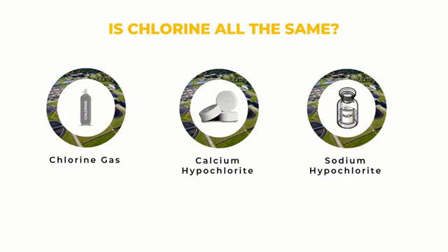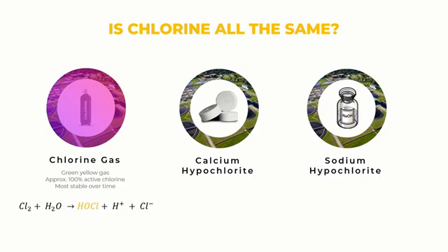Chlorine gas is greenish-yellow in color and heavier than air. Its high toxicity makes it an excellent disinfectant for water but also a hazard to humans who handle it. Because of chemical changes that occur when it is introduced into water, chlorine gas is no more toxic to humans when used to treat drinking water than other forms of chlorine. Chlorine gas, which is actually sold as an amber-colored compressed liquid, is the least expensive form of chlorine and is, consequently, the preferred type for municipal water systems.